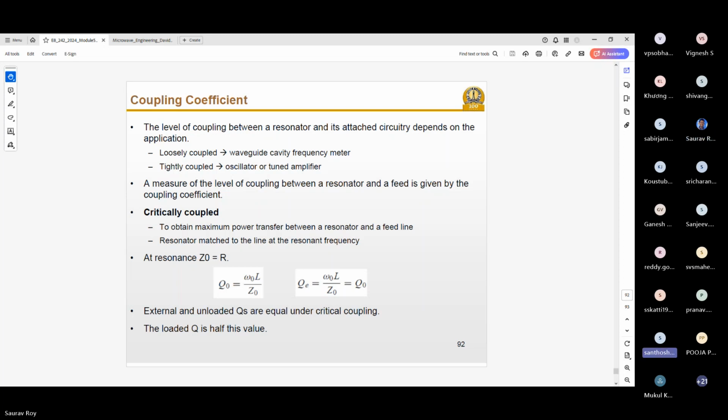I have another doubt. While tuning that bandpass filter, if you want bandwidth shifting, you will use capacitors. If you want flatness, we will do it with inductors. That one only we are tuning, that inductors only we are tuning.